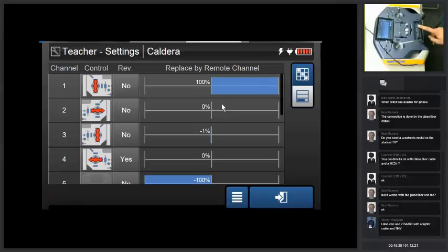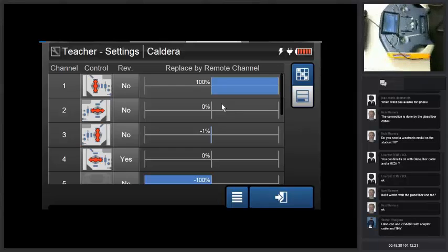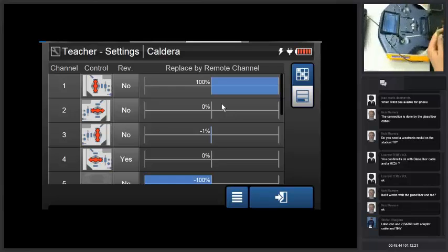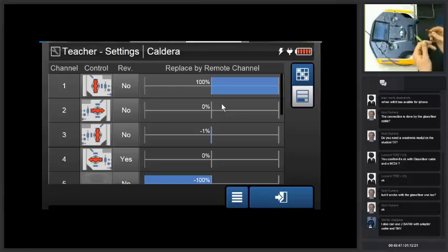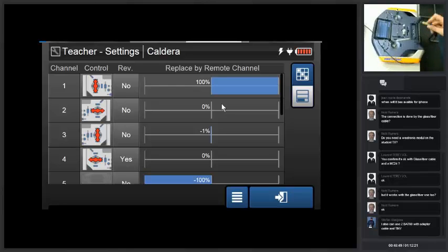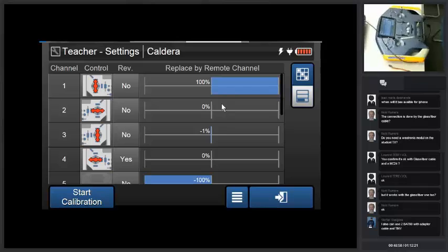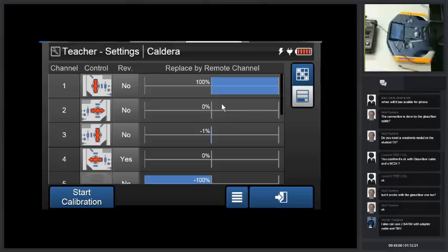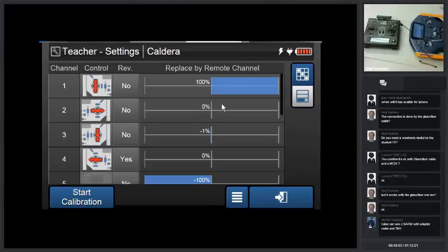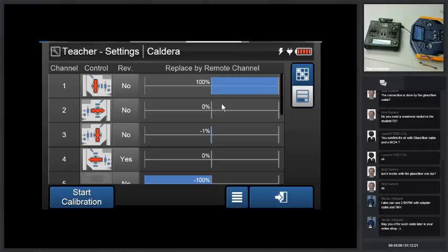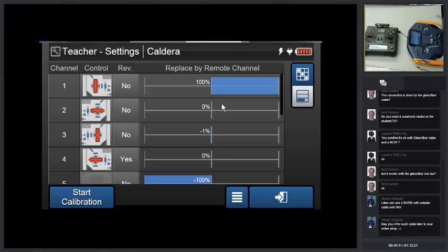It just would be necessary to build a little adapter cable from a normal servo plug to a 3.5 millimeter connection and power the tiny, and then you can have here the PPM output from the tiny or also from any other receiver. That doesn't matter too much. There just needs to be a PPM input, and then you can also have cable-less, wireless teacher-student functionality.